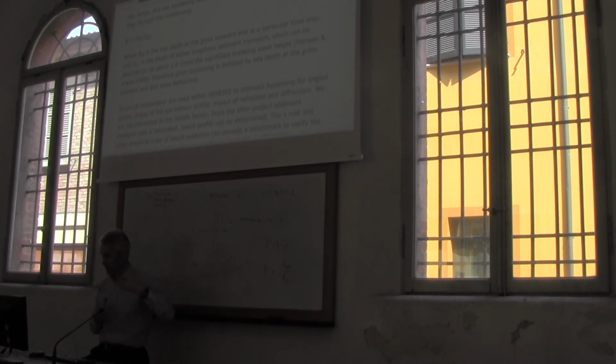So when you move offshore and you reach a depth DLT of the ocean, you don't have any sediment transport anymore. Of course, if this depth is equivalent to the depth of the groin at the toe, it means that the groin is extended over the active length of the sediment transport, which means that you don't have any bypass.